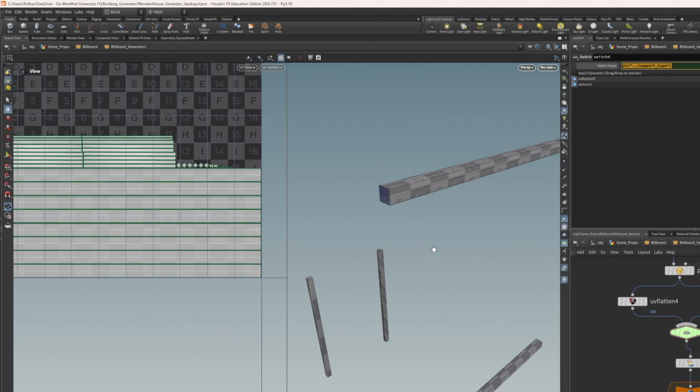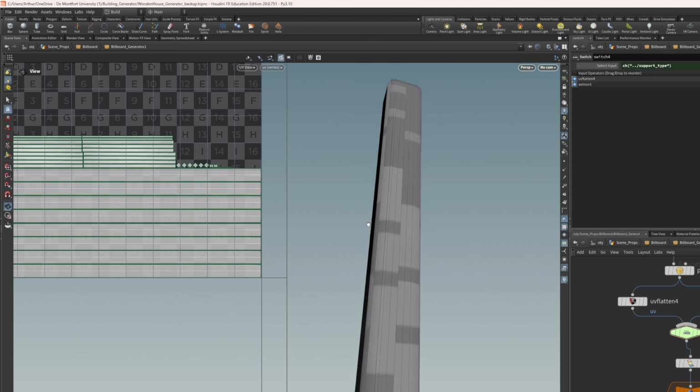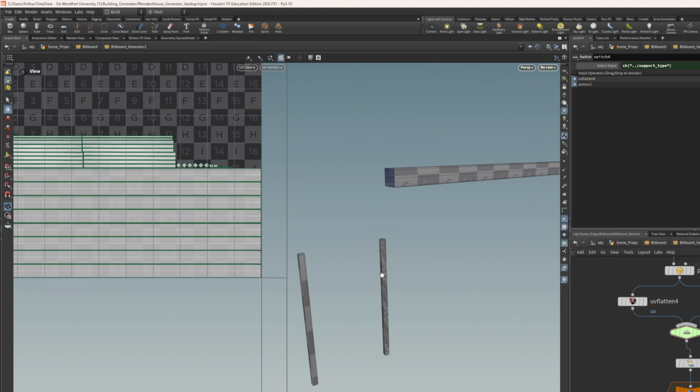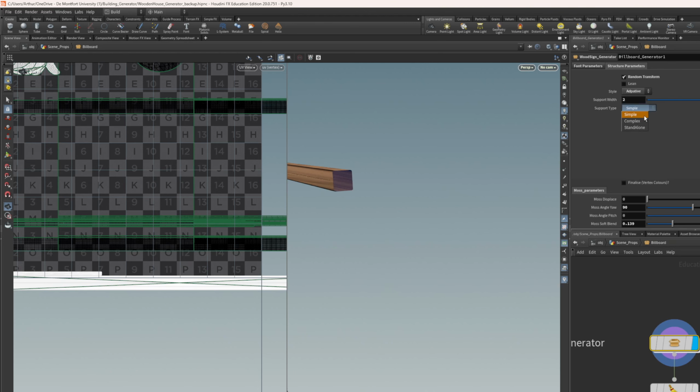So if you pick the first option on the list, it's going to come through as 0. Second option is 1. So right now, if we choose 0, it's going to show UV flatten. If we choose 1, it will show auto UV, and anything else I think will also come back with auto UV. Now, if we just quickly check, simple is the first option, 0.